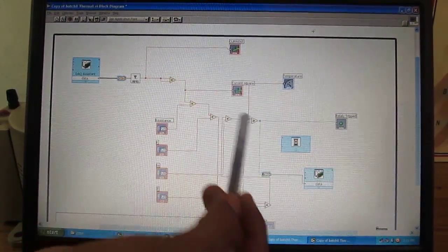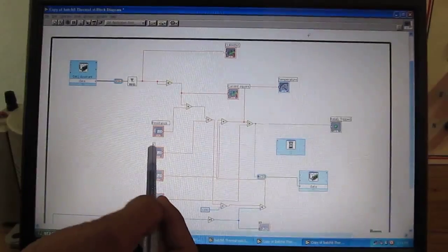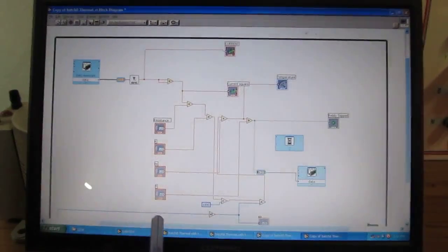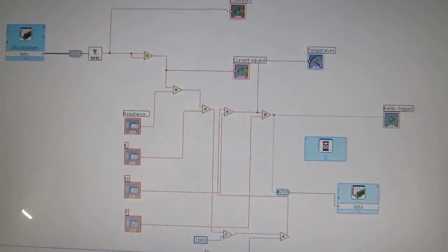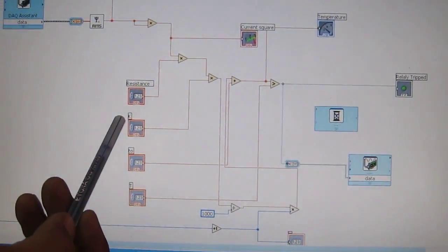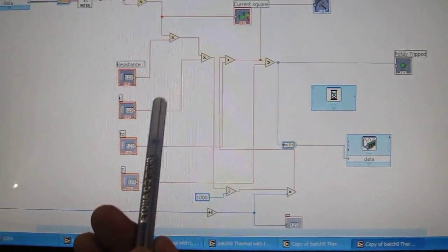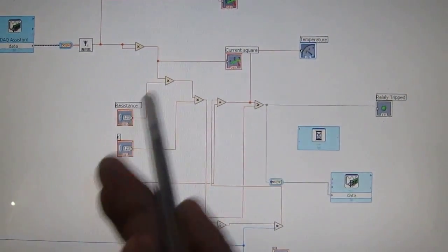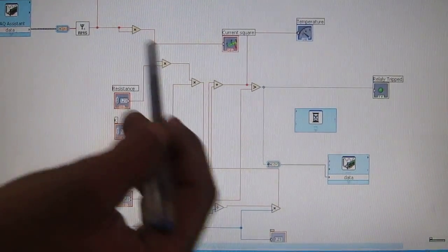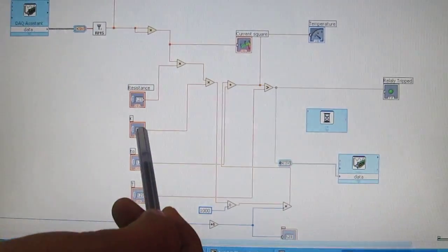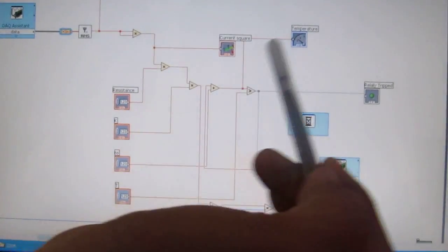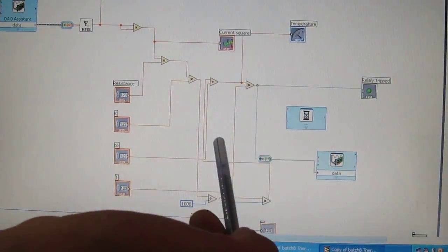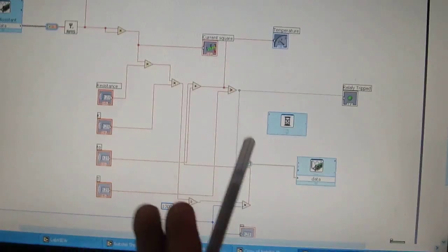That I square R component is in watts, so that is going to be multiplied by K. K is actually the machine temperature rise constant. As we gradually load the machine, how the temperature is going to rise, that curve's slope is nothing but this K value. K units are degree centigrade per kilowatt per second, since temperature is also a function of time. I am going to multiply the watts, which is the actual component of heat, with this K. The entire product will give us just degree centigrade, which is the actual temperature.